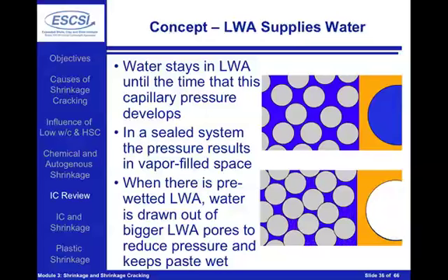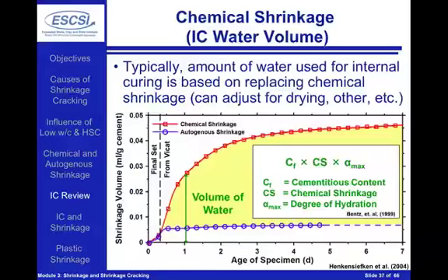As that water is drawn out of the lightweight aggregate, it's going to keep the paste saturated, it's going to keep the paste full of moisture, and it's going to be hydrating more of that system, and it's going to be reducing the overall shrinkage that's taking place in that system.